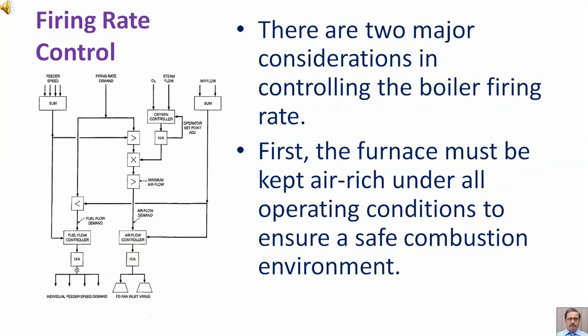There are two major considerations in controlling the boiler firing rate. First, the furnace must be kept air-rich under all operating conditions to ensure a safe combustion environment.